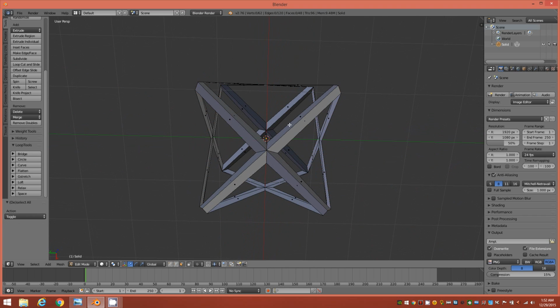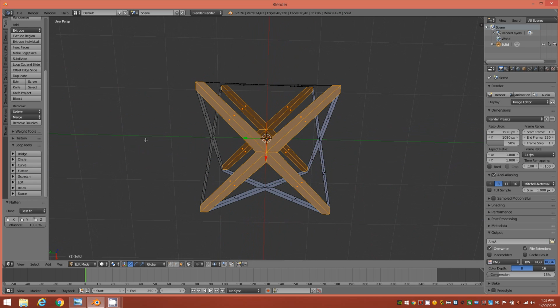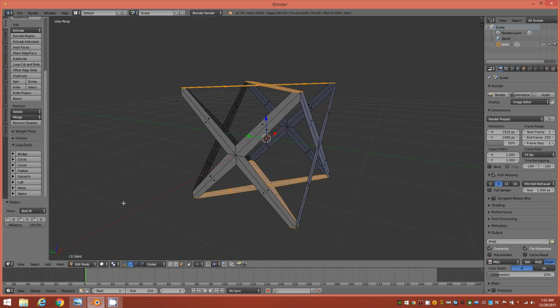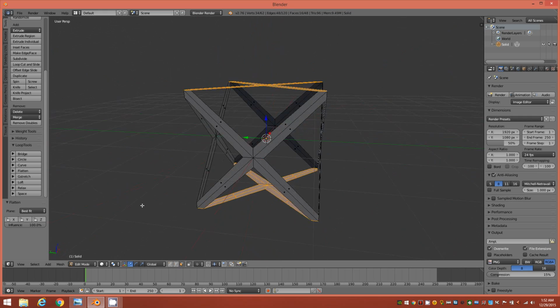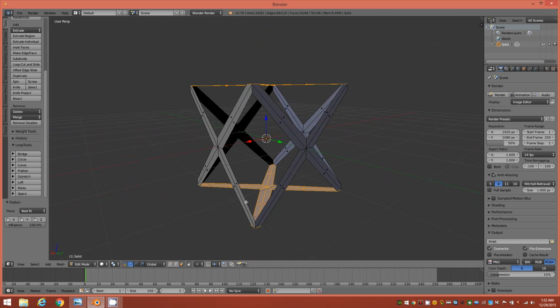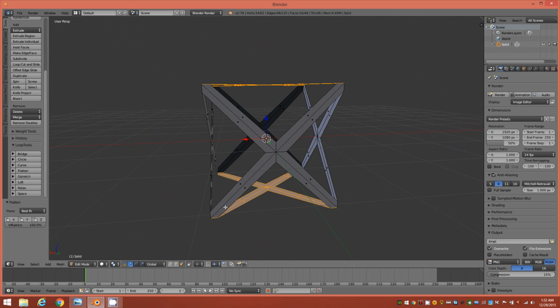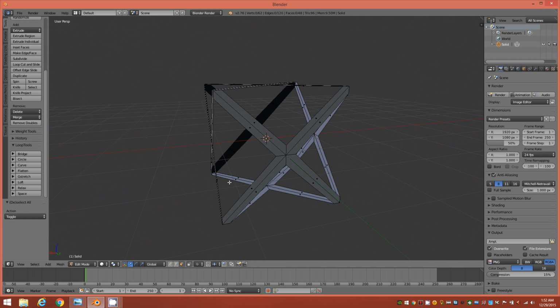So deselect, tap your C key, select those faces and those faces, drop the tool, and then flatten again. Now you can tumble around and see that it's done a nice job of planarizing all of those sides for us. Now tap the A key to deselect.